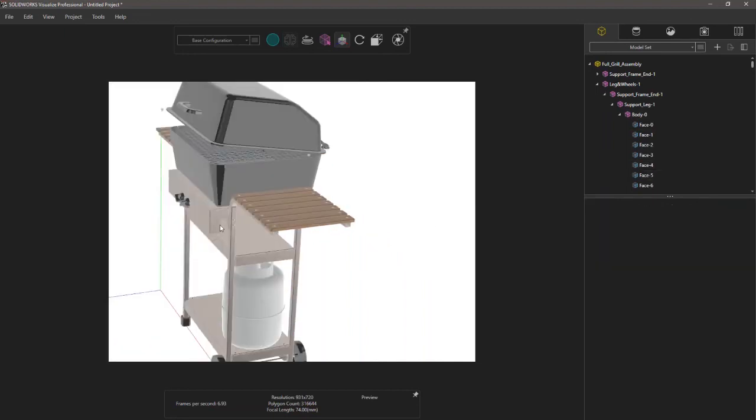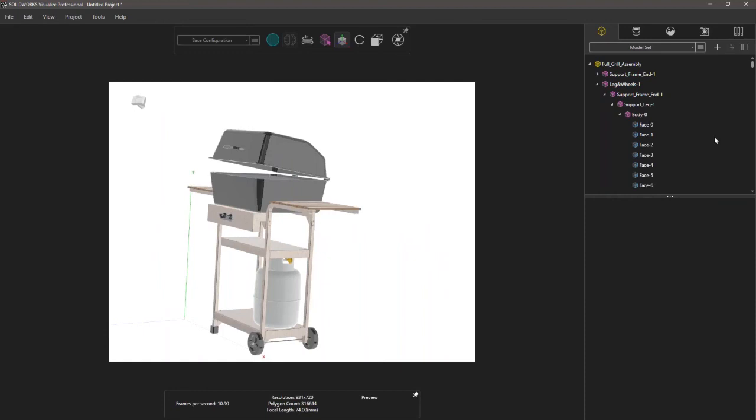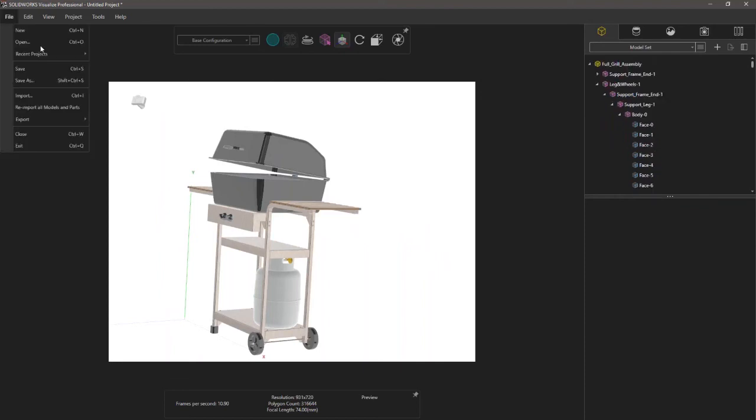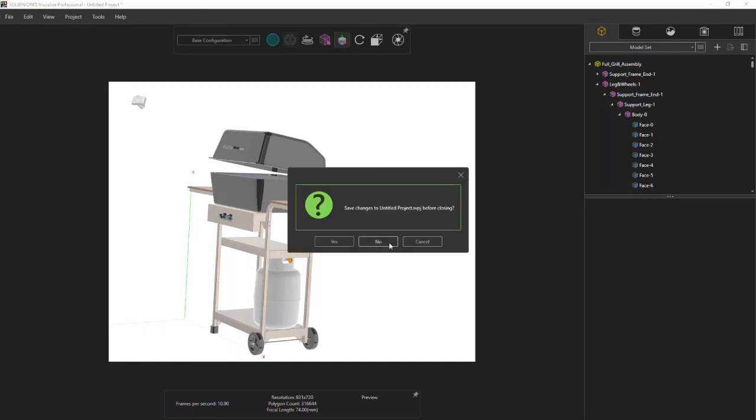It doesn't show up in the polygon count, but there's a lot of overhead because look at all the faces in just one body that are being isolated as separate parts essentially. So I'd advise everyone to never use retain structure except on a very simple example that they're sure their system can handle. Use the appearance grouping if you want to group the appearances, or the automatic if you want the ability to select them individually.